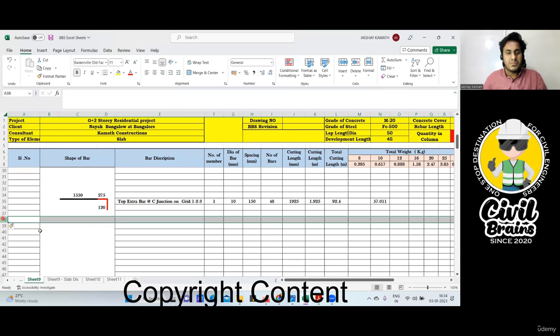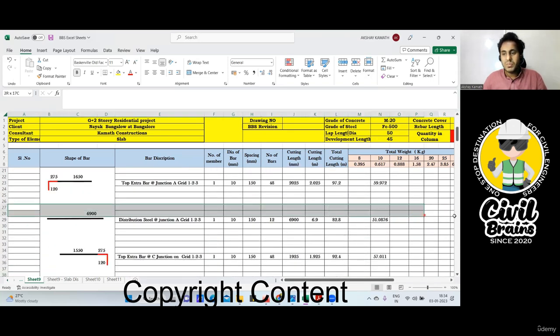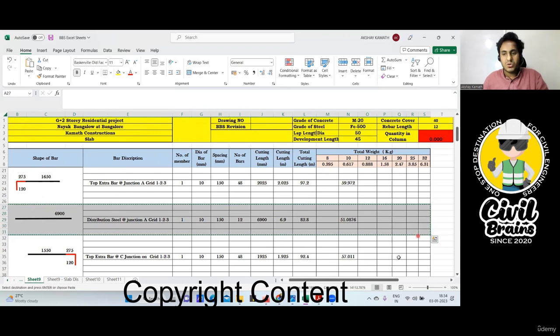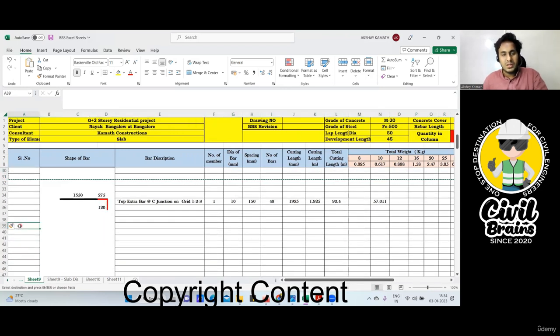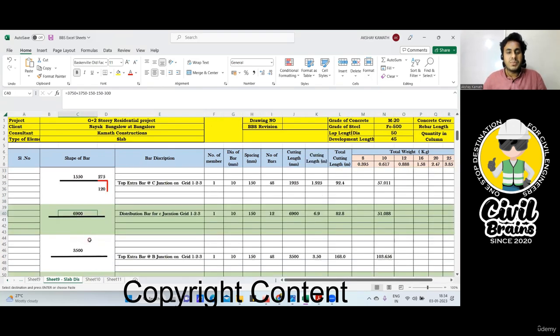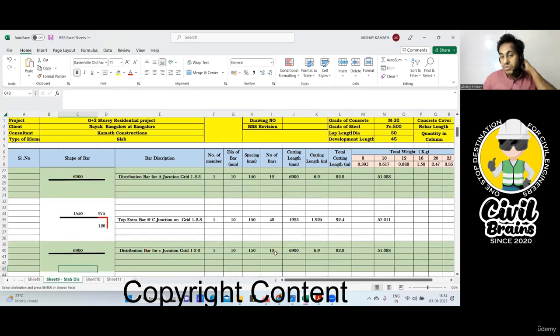Increase this thing. Okay. Then you copy this part, Control C, come here and paste it here. Control V. Got it, no? And then you do the calculation, whatever you are supposed to do. Already I've done and kept it. So the same thing will happen. Cutting length is 6,900. Only the number of bar will change.